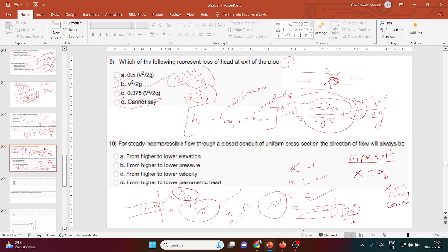So if you calculate this velocity, this is the highest velocity achieved by your fluid. Based on that, you design everything. Before the development length, the velocity is not achieving its maximum. This is the reason we calculate everything after that, so the system will be stable. Based on that, we assume further design. Will the stress be higher at that region? Yes, stress will be higher at that region.